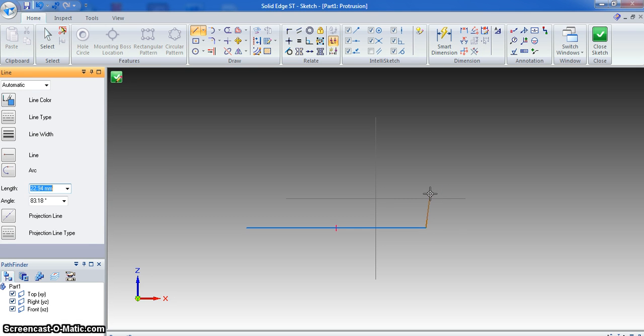Now if I work it out, 72, that's the full height. Take away the 2 smaller heights, 32 and 20, actually gives me a result of 20. So I'm going to type in 20 over on the left, and then it wants to snap to a point, which is a bit of a problem obviously because I don't want it to snap to a point. So I'm going to actually put in the angle as well, 90, so it goes straight up and down without, you know, trying to snap to one of those reference planes. Now I need to come in 50, so I'm going to type 50.